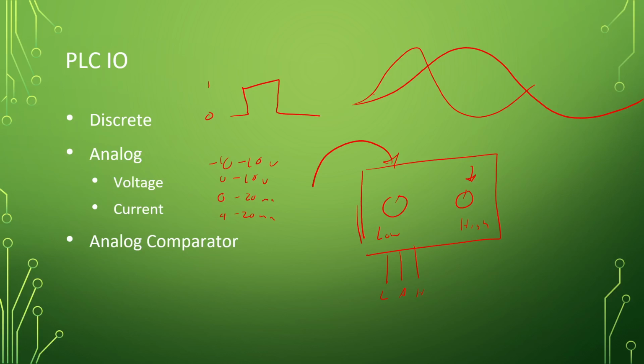But anyway, the analog comparator, it's just really nice because you can just tweak those dials ever so slightly as the system's not running. Load a part in and say, this one's just barely too short. You just turn the dial until it turns on. Then you put one that's just barely too high in and you turn the dial till it's there, and it's like, okay, now we're good. And that's how you tune the system.